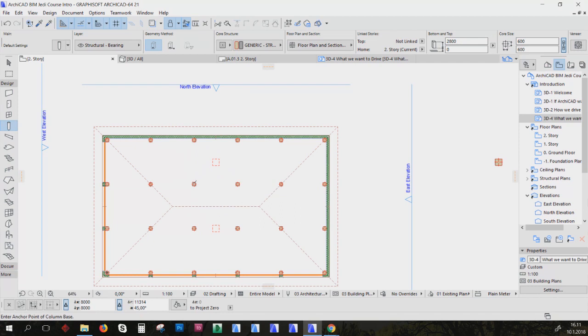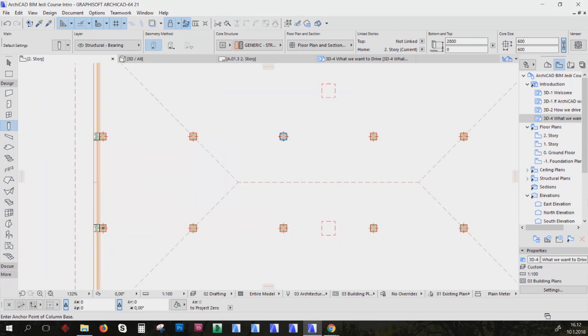That I've quite often worked, which was probably the old school way of checking distances, is setting your origin point somewhere. If you wanted to check that all the posts are in the right line, you can set your origin point there with Alt Shift, and then that becomes 0, 0, and then you can just run your mouse along, and if you've got this coordinate box in the bottom showing, which I have on all the time, I find it real handy, you can quickly see that it's 4 meters out from there, and that one's 8 meters out, and that one's 4 meters out, 4 meters up.